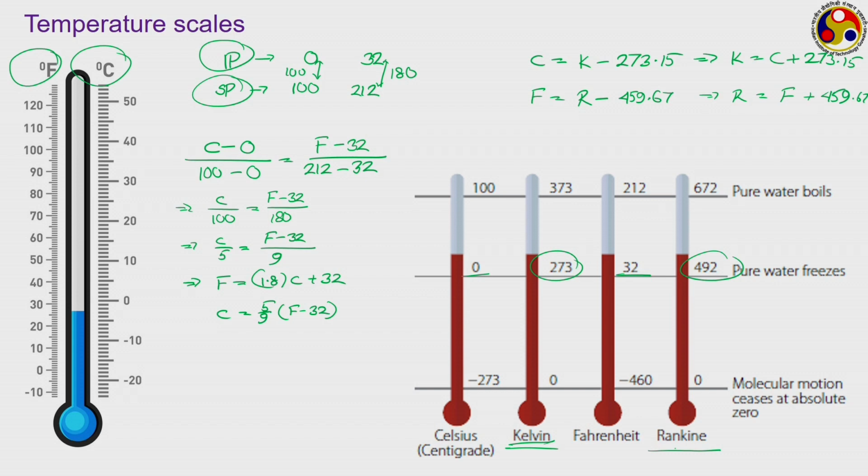Actually, Kelvin and Rankine scales are called single point temperature scales. Why they are called that we shall be discussing shortly. But whenever we are talking about single point temperature scales, generally the degree symbol is dropped. Like 2 point temperature scales, we use the units as degree Celsius and degree Fahrenheit. However, in case of single point temperature scales or absolute temperature scales, we use only K to designate Kelvin and only R to designate Rankine.